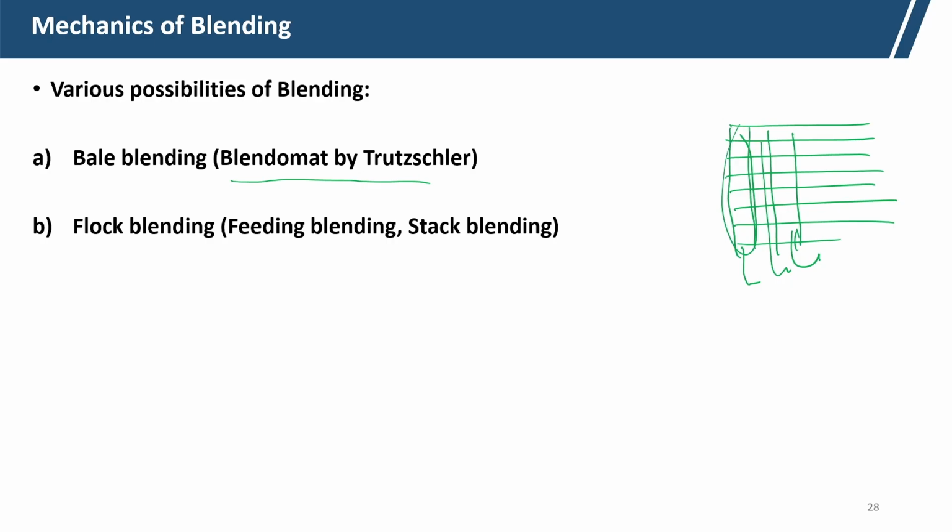Lap blending is also there, although nowadays lap does not exist in most Blowroom lines. Lap blending is where uniform blend is possible at the carding stage. Sliver blending takes place in the Drawframe.